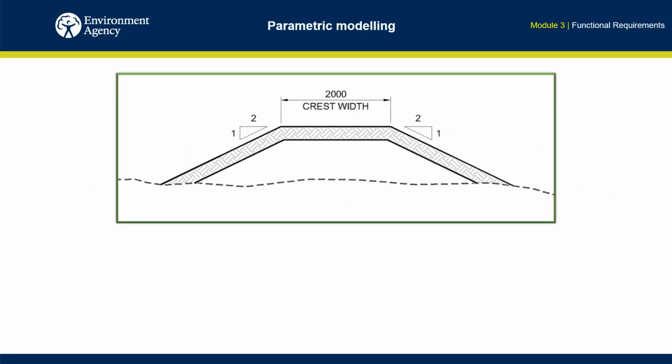Parametric modelling is a tool within drawing applications that creates smart objects. A parametric object is one where its size and appearance in the model is defined by setting one or more parameters in the CAD software. Parametric fields can include geometry, materials, and finishes. By adjusting the settings of each parameter, the appearance or shape of the object can be changed very quickly compared to redrawing it.